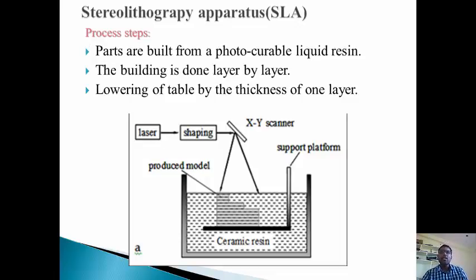The stereolithographic process creates three-dimensional plastic objects directly from CAD data. The process begins with a vat filled with photocurable liquid resin. The operator first loads the CAD data model into the system, and the required support files at the same time. The computer controls the optical scanning system and directs the laser beam so that it can solidify the two-dimensional XY cross section corresponding to the slicing, on the surface of the photocurable liquid resin to a given depth. The laser then moves to the next layer. This process continues, building the part from the bottom up until the system completes the part. This is the basic principle of the stereolithographic process.